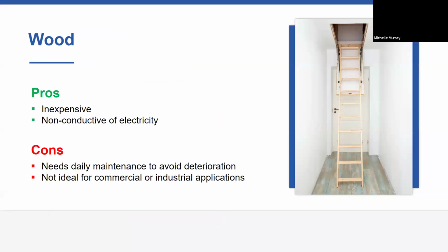So first you have wood. It is a great popular choice since it's affordable and readily available. As long as you take proper care of them, wood ladders can last a long time. When they're dry, they're great as a non-conductor of electricity, which makes them a top choice with fiberglass for work that may have electrical hazards. Despite this, wood ladders are not appropriate for all industrial or commercial environments, as they're prone to rot, fungus, mold, or pests.